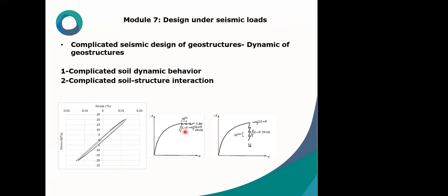And what's ratcheting? Let me explain a little about ratcheting. At the smallest strain ranges, a granular soil has incrementally nonlinear behavior with a high stiffness that gradually decreases with increasing deviatoric stress. The soil model should be able to predict higher initial stiffness after reloading. If not, ratcheting is eliminated. It means cumulative strain during cycles causes ratcheting, and it should be considered in the soil models.